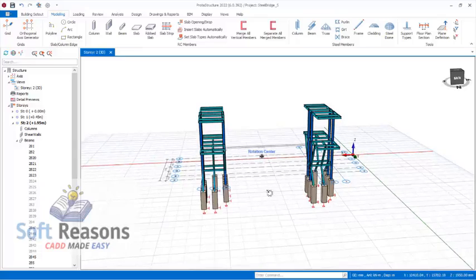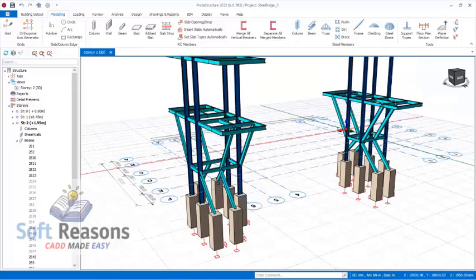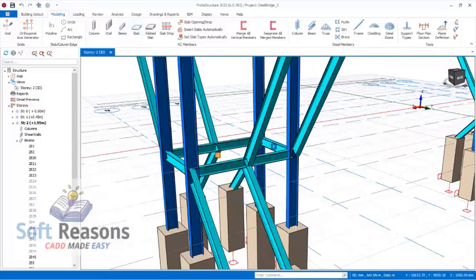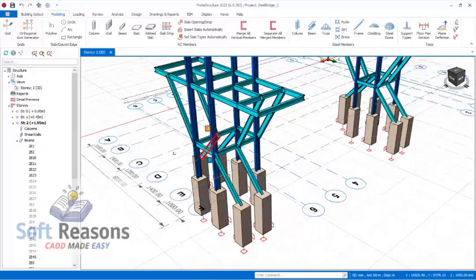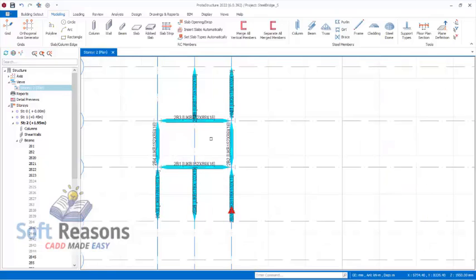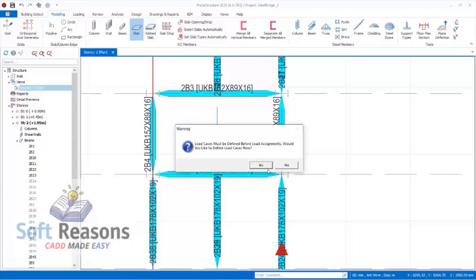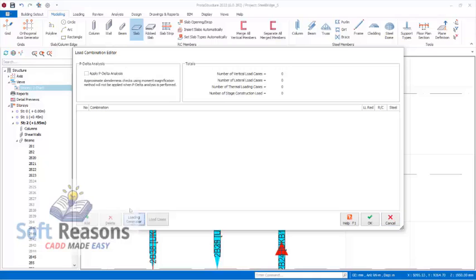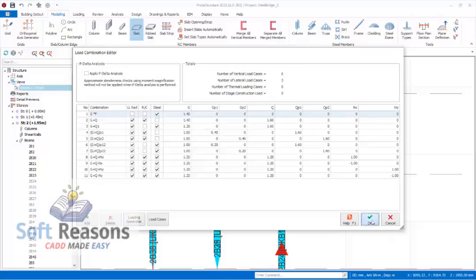So the next stage we will be considering the reinforced concrete slabs right here. So we are going to be using the RC slab to actually transfer the loads to the steel beam members successfully. So for you to do that, we are at level 2, so you just have to navigate to the plan view. This plan view, you have this. So select reinforced concrete slabs. Yes option. So we have to generate the loading successfully. Click on OK.